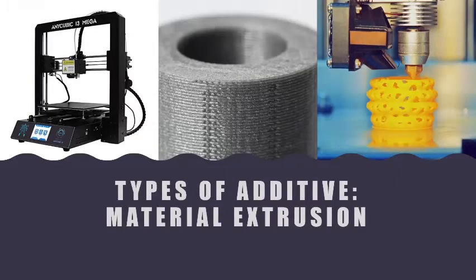Material extrusion, also called fused deposition modeling, is one of the most common types of 3D printing. Most desktop printers belong to this type. It consists of a polymer filament that is extruded through a hot end. There are a lot of materials that work perfectly, like ABS, PLA, polycarbonate, nylon, PETG, even chocolate and clay. But materials like metals cannot be printed this way because of the extremely high temperature gradient within the part.